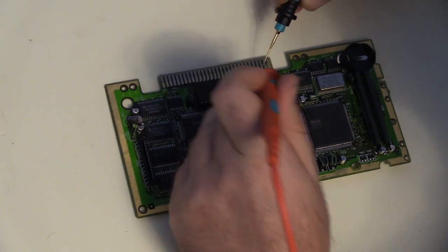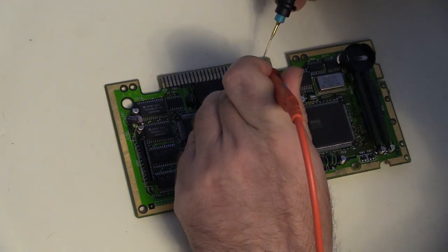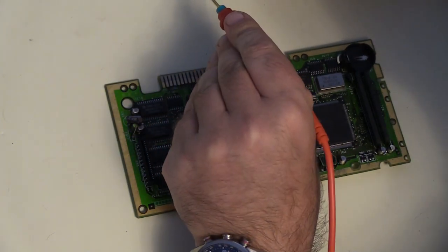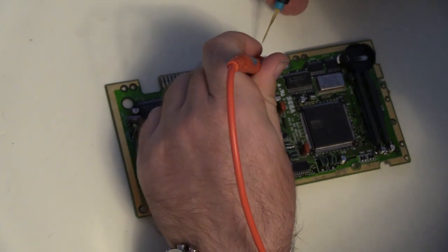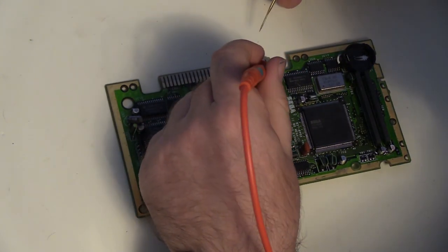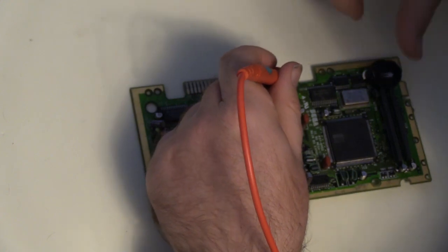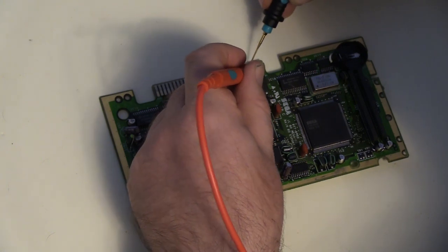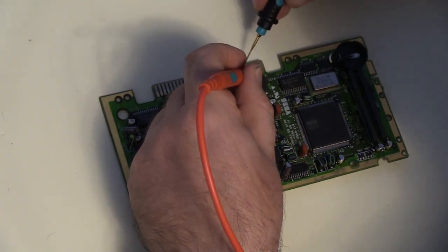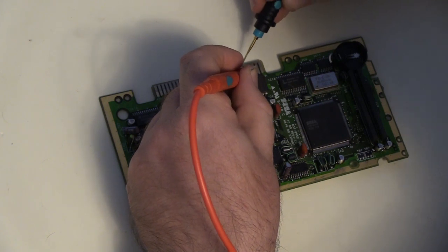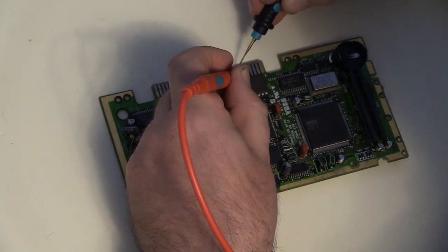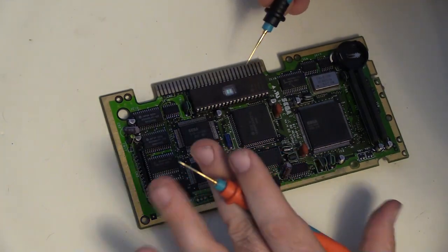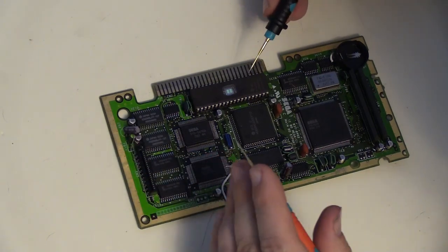Starting here, this is address line 0, and we can see that it has continuity. Anytime we get a beep, that means we've got continuity. Actually, A0 starts here at the very bottom, the bottommost pin. And so we can see there we've got continuity, and then the next pin up, and then the next pin up, and so on up the entire address line. That's where the Genesis reads these lines for setting what data it's going to read off this EPROM.